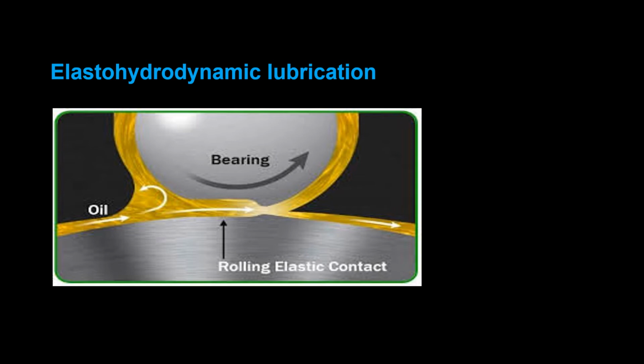Insufficient surface area, a drop in the velocity of the moving surface, a lessening in the quantity of lubricant delivered to a bearing, an increase in the bearing load, or an increase in lubricant temperature resulting in a decrease in viscosity, any one of these may prevent the buildup of a film thick enough for the full film lubrication. When this happens, the highest asperities may be separated by lubricant film only several molecular dimensions in thickness. This is called boundary lubrication.